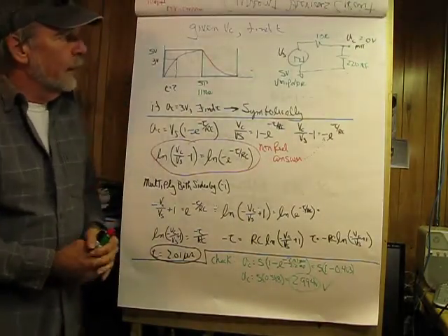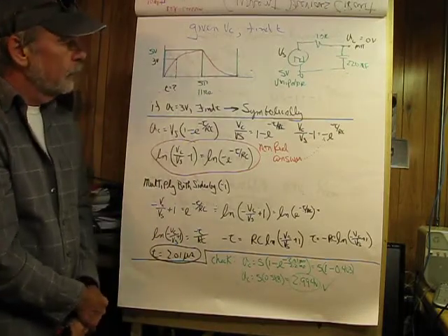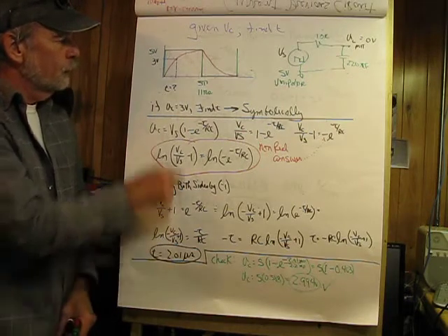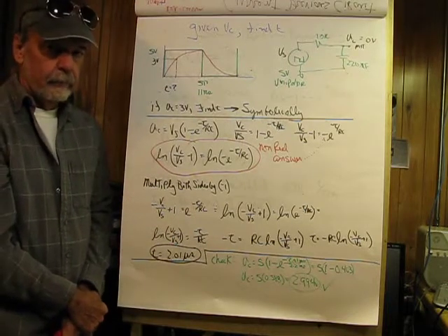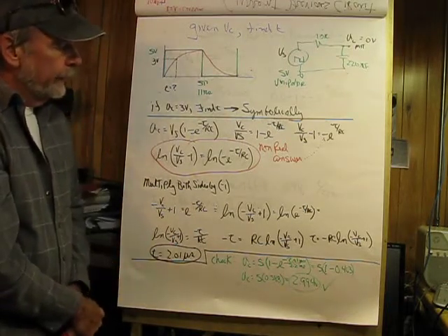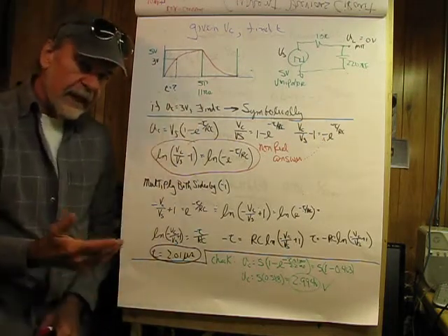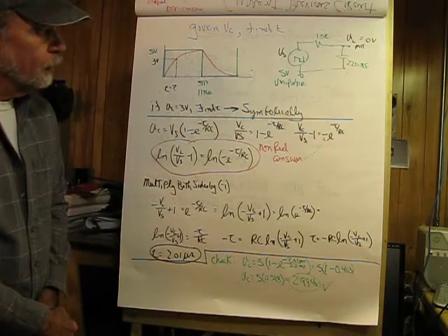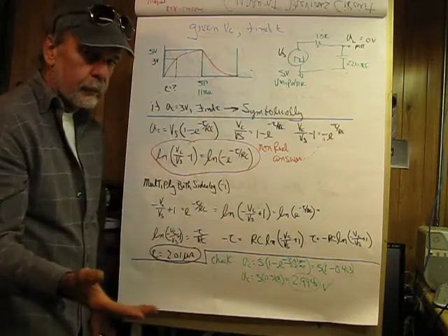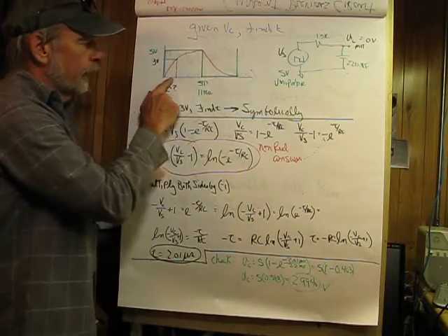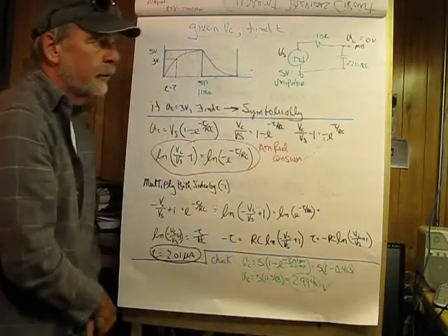Alright, last thing we want to do is, given a capacitor voltage, find T. So if I let VC equal 3 volts, what is the time? When does that occur? This would be 5 tau or 11 milliseconds, and the time constant of our circuit is still 2.2 milliseconds. In this case we have a unipolar pulse, I'm trying to make this a little bit simpler, meaning it's only going to go in one direction, and VC initial is going to be 0 volts.